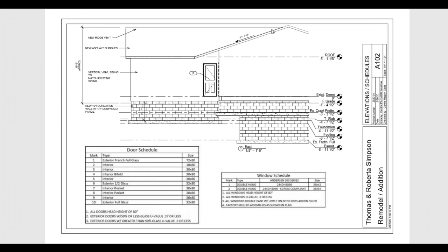There's another part of the house that has a full basement, and that is shown behind, and this would be the bottom, the basement level. And then the new has a crawl space, and we probably would have done the same height crawl space as this, but I wanted to make sure that it was at least 3 feet 7, 3 foot 6, somewhere in that vicinity below frost level.